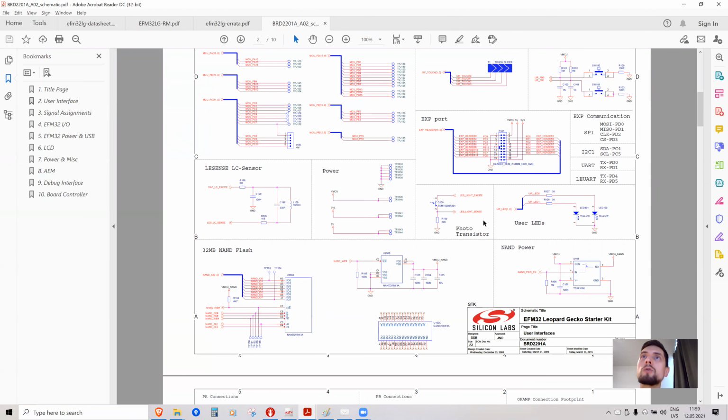And the thing is that usually it's a good practice to put some capacitor between the analog signal pin and ground, or if it's a differential signal between the differential lines and from both differential lines to ground, capacitors which are 10 times smaller than the one that is between the pins.